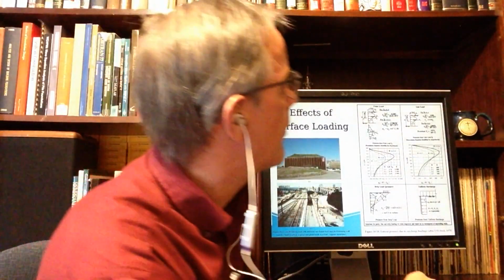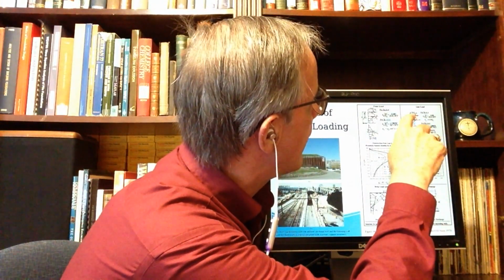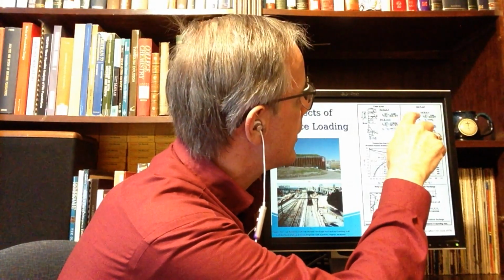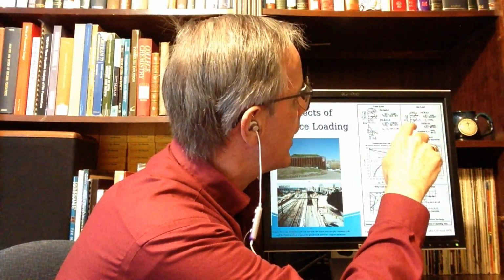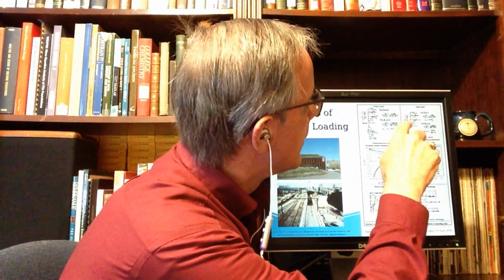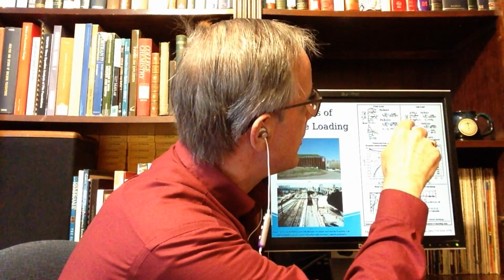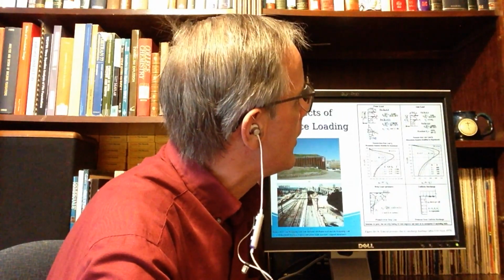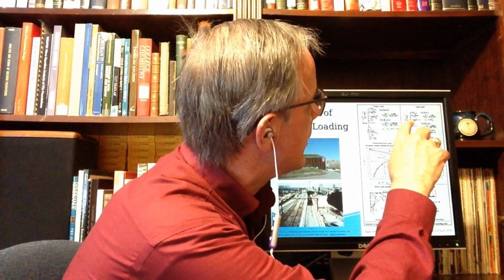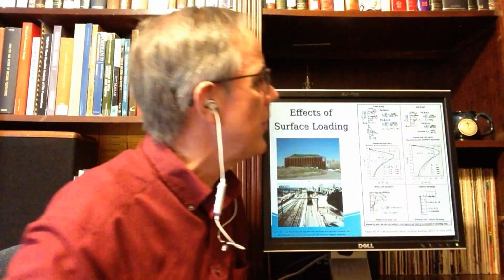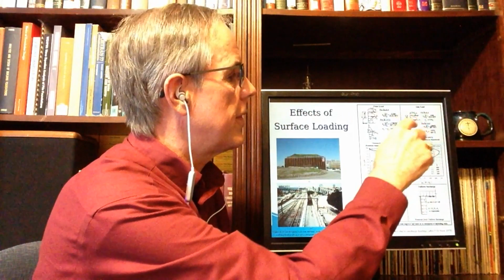You notice the equation for the line load, you've got M bar values, which is basically the ratio of this length to the height. For any point along there, you've got the ratio between this and the height. So you use the N value, which is the ratio of z to the height here, and you use those in these formulas to get a profile.